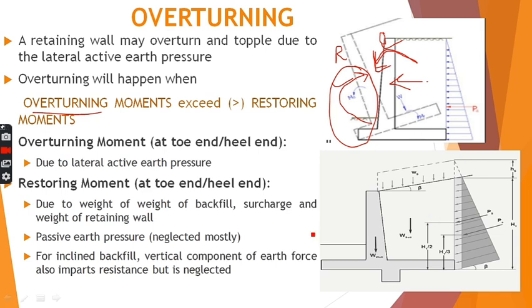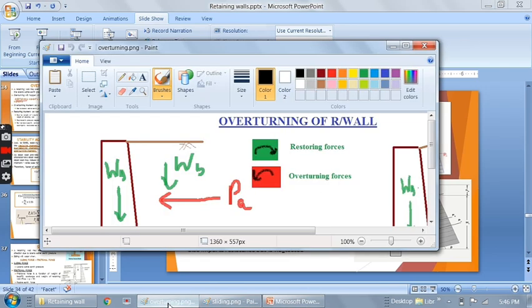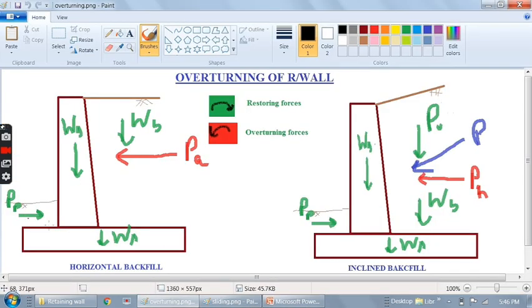I will explain it in detail here. So look at both these diagrams. First we look at this particular diagram. Here we have a cantilever retaining wall acted upon by earth pressure PA. As is clear, due to this PA force, some moment will act which will lead to its toppling or overturning. So let us consider a point here at the base of the toe slab.